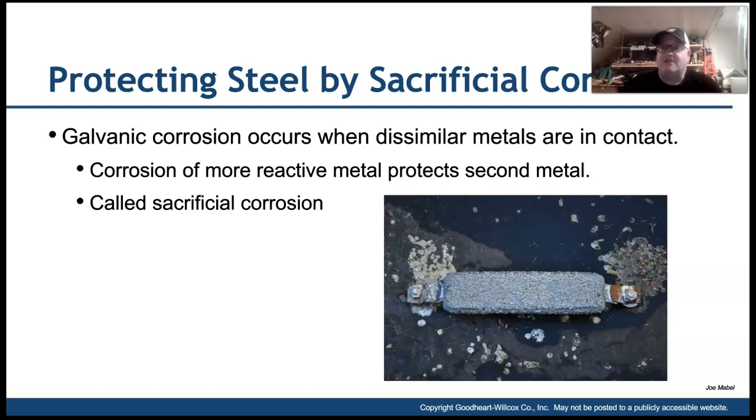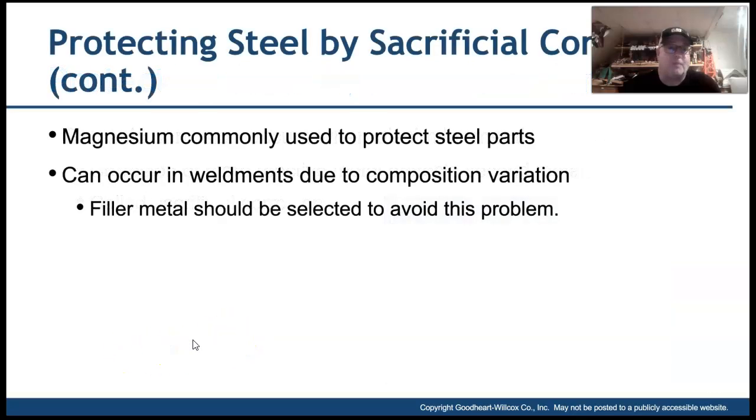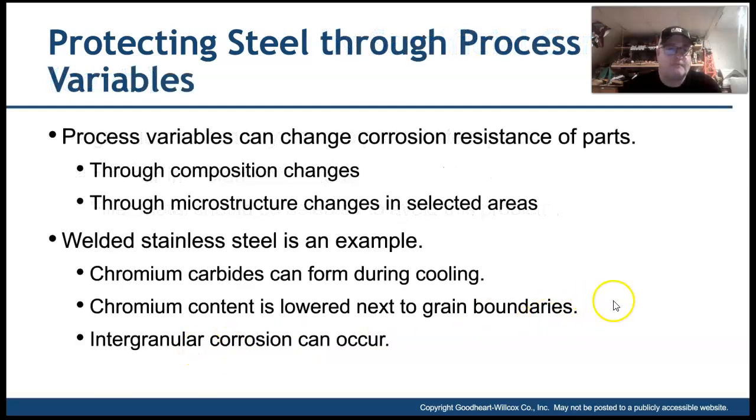Now, maintenance guys and gals, you are going to need to be much, much more familiar with galvanic corrosion and selection of bolts and washers and other types of fasteners because, if you're not aware of this, you may unintentionally cause things to rust and corrode prematurely as well. So we want to pay attention to that as we go through here. I'll let you go ahead and read that. We'll talk more about galvanic corrosion in that lab here.